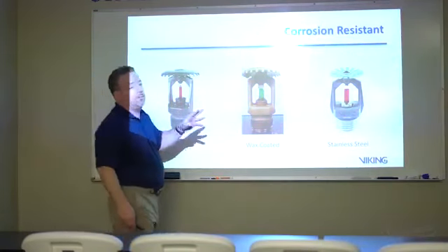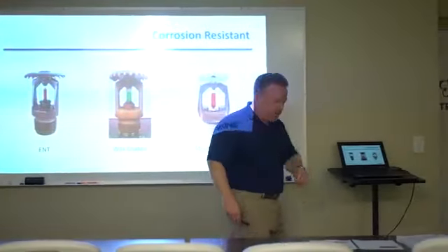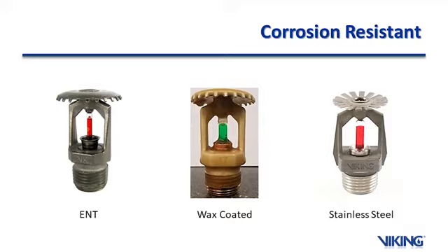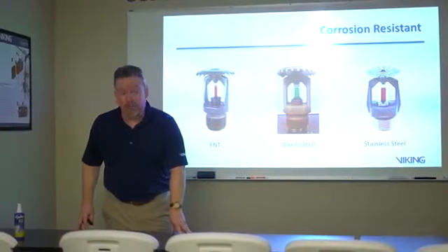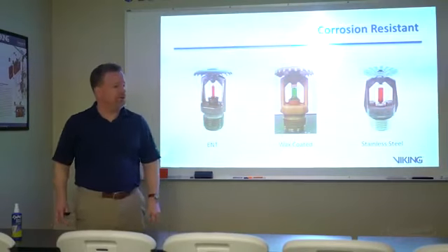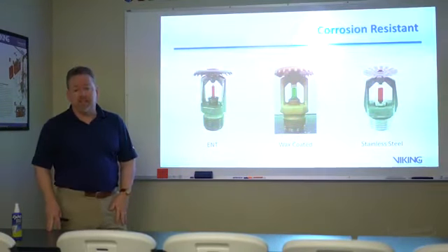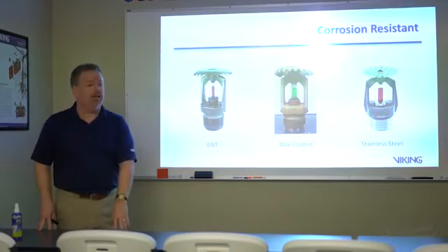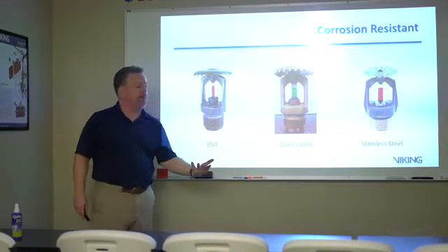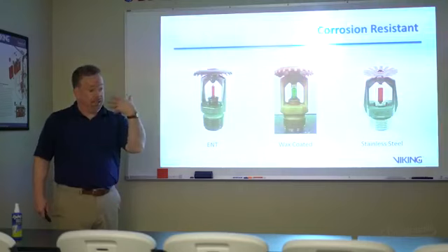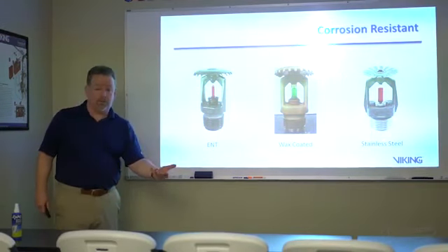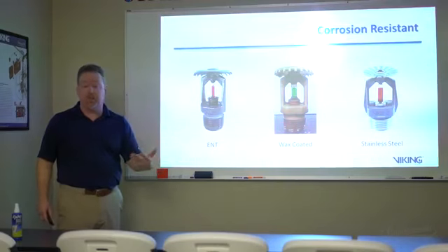Then finally, we have to be concerned with corrosive environments. Now, corrosive environments exist in quite a few different locations, one of them being right here in South Florida, right along the coast. We put sprinklers in places like parking garages. Yeah, those are considered to be corrosive environments because of the salt air. So when you look at NFPA 13, it considers outdoor parking or parking garages in the coastal areas to be corrosive environments.